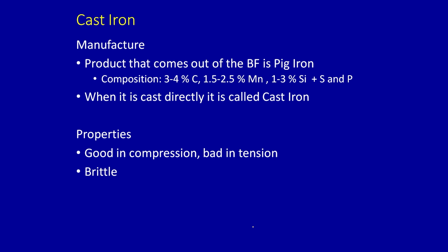vibration resistance because of the presence of graphite as carbon. Carbon is present as graphite, not as a carbide here. In steels, carbon is present as a carbide. It reacts with iron, but here because of silicon, it does not react with carbon, and it forms carbon flakes or round separate carbon. There are different kinds of cast iron present in the world.